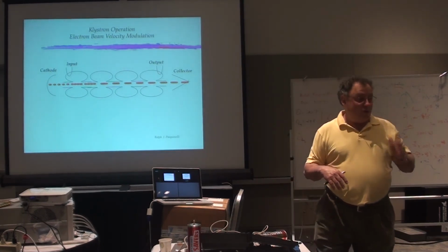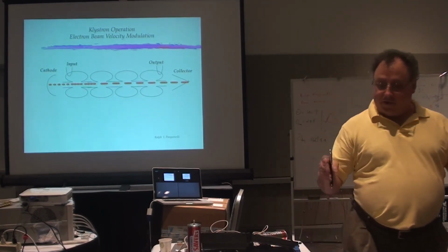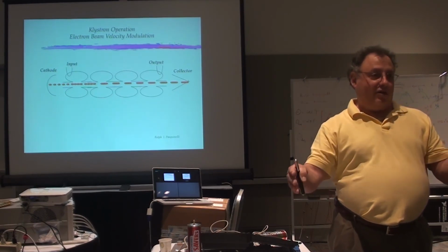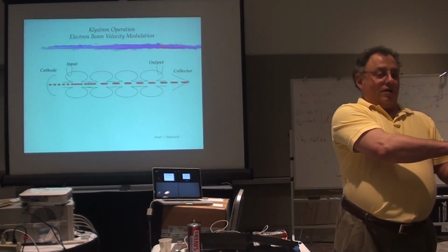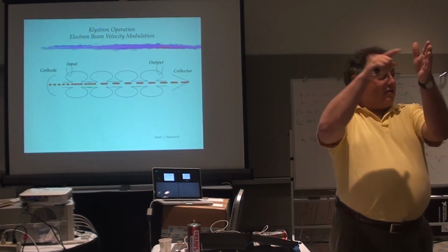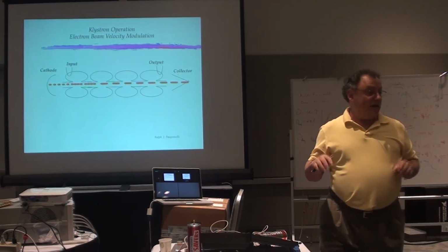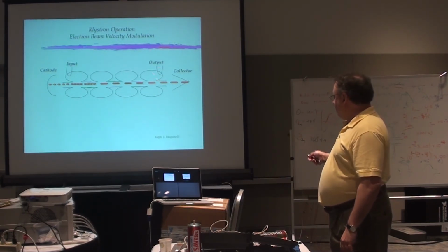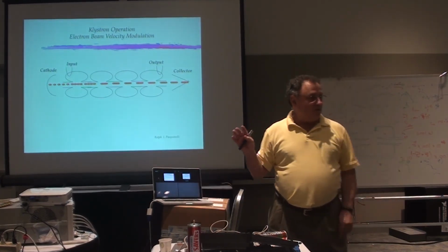So that's why you want to worry about that, and that's why many times you'll end up putting a circulator there, or you end up putting a very fixed number of integer half wavelengths between your window and your cavity. Because what happens on a half wavelength, if there's a node here, then a half wavelength later, it's a node there, okay? If this was a quarter wavelength and there was a node here, a quarter wavelength later, it's a high voltage point. That's bad. So at Fermilab, we don't have circulators on our outputs, but we run at only one frequency, and of course, the amplifiers can take the reflected power, but you don't want that high voltage to happen at that window, to save the ceramic break on the tube.